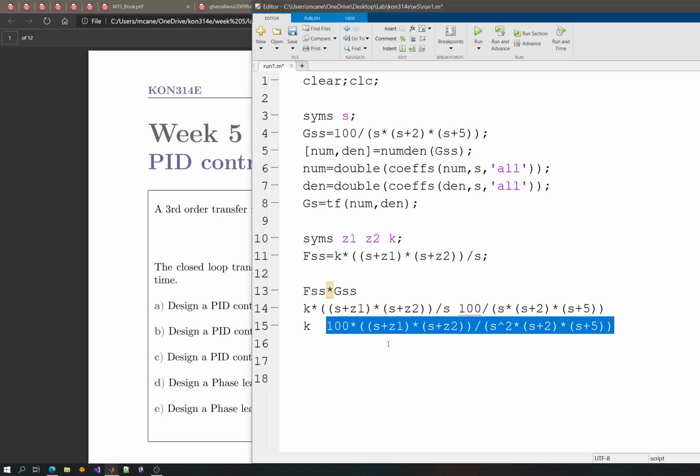I'm looking at the root locus, how the branches look, how I can choose this desired point, and what happens to the remaining elements. Once I'm satisfied with the root locus that is generated, I will add these zeros and poles, look at this root locus, and calculate the gain. Calculating the gain is basically the design of a P-type controller.